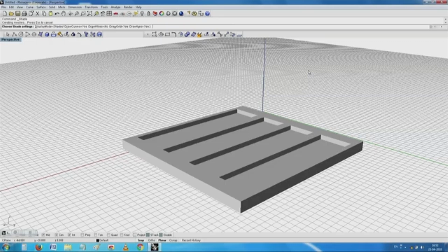This is where I wanted to tell you we have three axes, x and y and z. X and y depend tremendously on the basic resolution and the nozzle characteristics and so on. The z or the vertical axis, the slices, depending on the complexity and the build of the machine, may or may not have the same type of resolution as the other things. So, the first one, the base has been built. After that, part of the ribs have been built. Now, I will again undo it and show you.